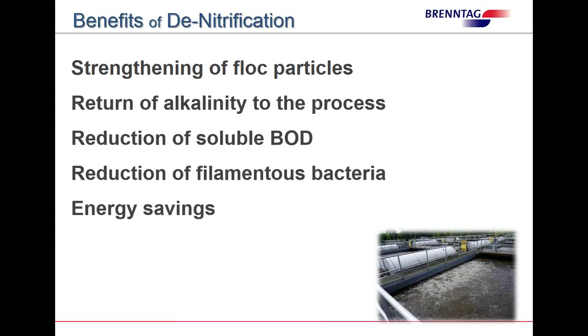And if we turn the blowers off and we're not adding as much air, we're going to save electricity. So we're going to get an energy savings. And as a good friend of mine up in Wisconsin says, you get tough bugs. They're going from a fully oxygenated atmosphere to a totally non-oxygenated atmosphere. So we get tough bugs.